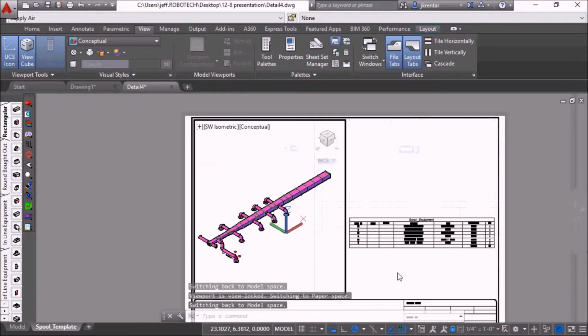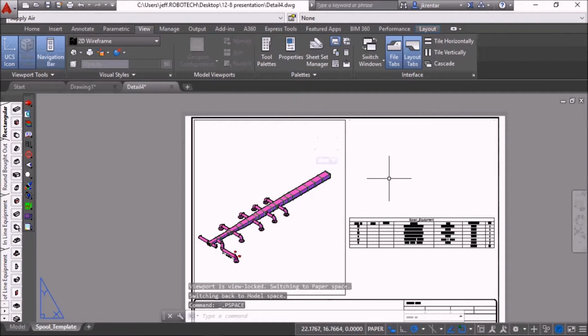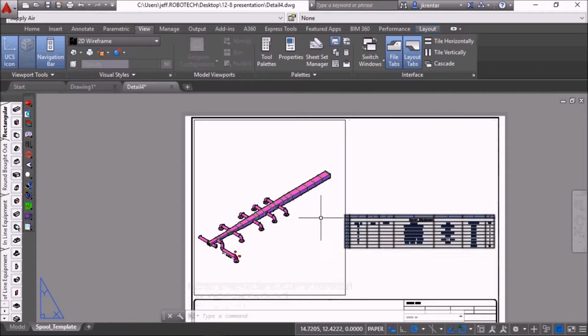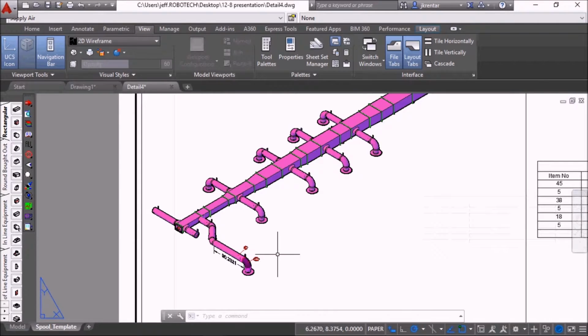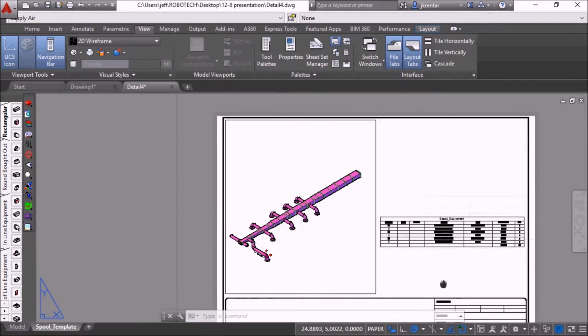And it's just like AutoCAD, a lot of the same tools that we're doing by editing the viewport scale and adding text. The spool dimension command is really great. You could use the regular AutoCAD dimension tools as well. They'll work as well, but the spool dimensions are a little bit easier to snap to and align to the specific duct. So those are really great tools.